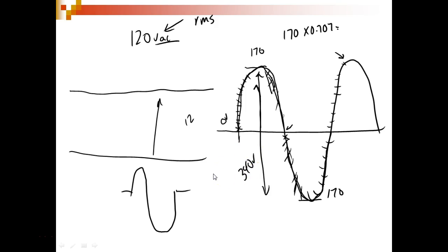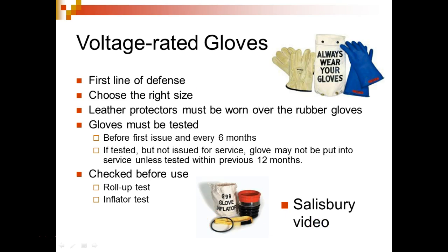So there's the categories, guys, and this is why normally when they rate these things, the AC voltage is rated less, because your surge is going to probably be riding above that upper pulse up there, right? So even though it says 120 volts, we've got 340 volts peak, but we're only looking at one side of it, 170 volts, right? Y'all understand that? So that's why AC is rated lower, because the surge could occur where? Could occur up there at the top, right? Y'all understand that? Okay, good. Any more questions? Good questions, guys, even though that had nothing to do with the class.